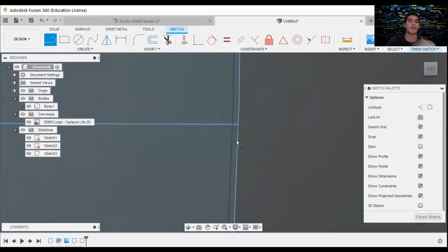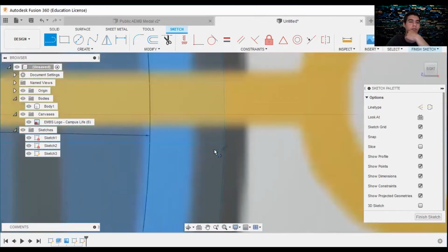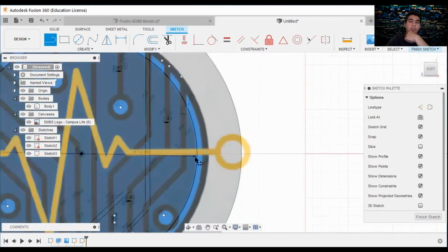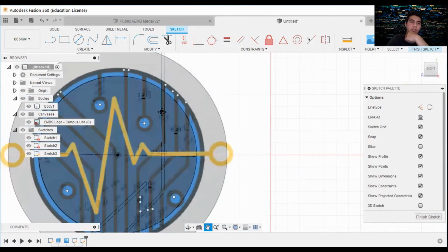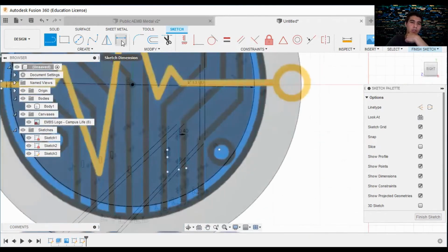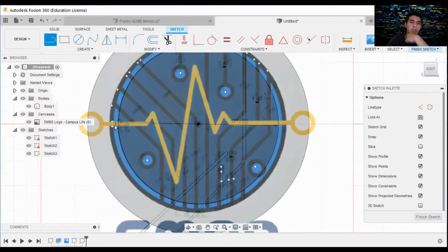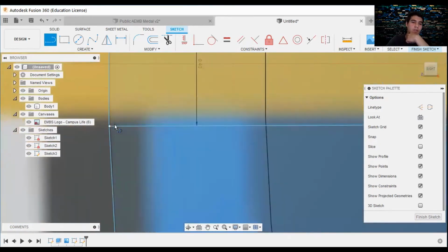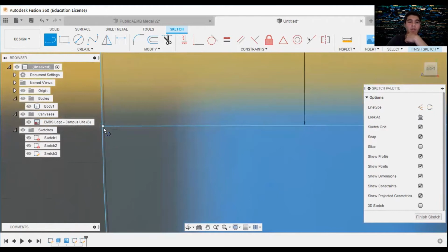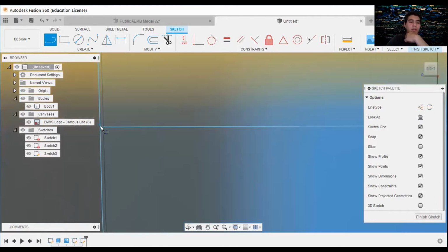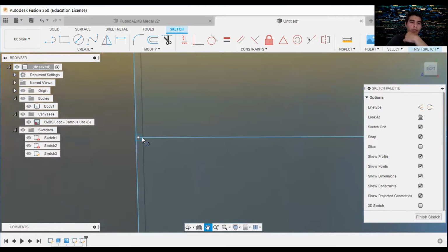So what do you know now? You know how to do surface offset for sketches. You know how to trim. You know how to use these properties for constraints to make things perpendicular. You know sketch dimension. You know how to create circles, how to copy and move sketches. And how to do rectangular patterns. How about that? And you know how to proof check your sketches so that when you extrude it, you don't have to go back and edit sketches, since you'll know everything in your sketch is defined.